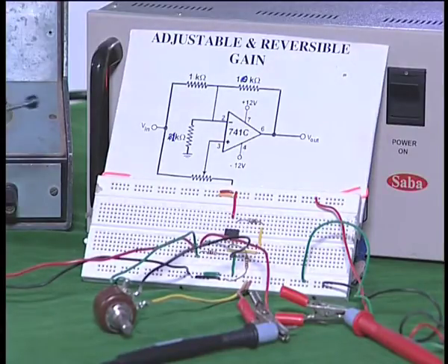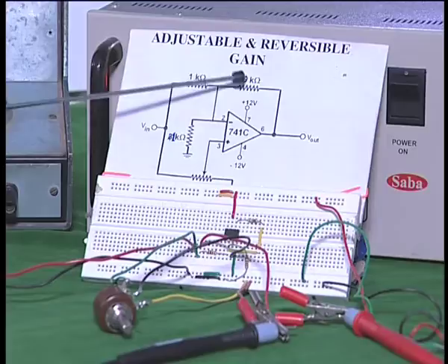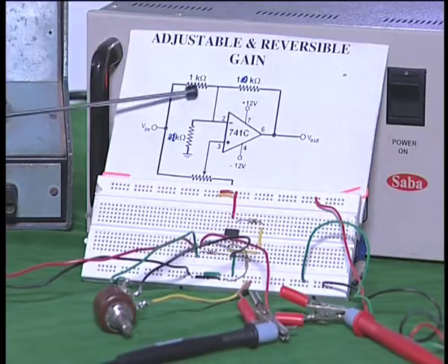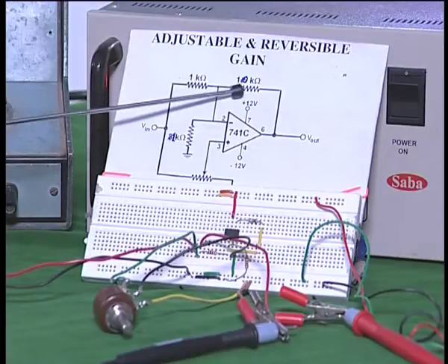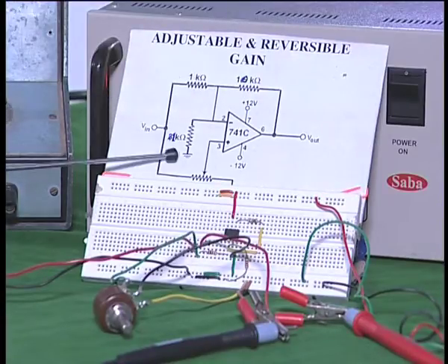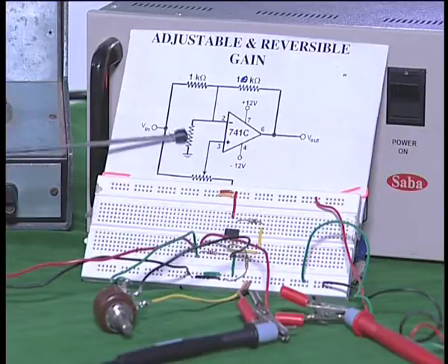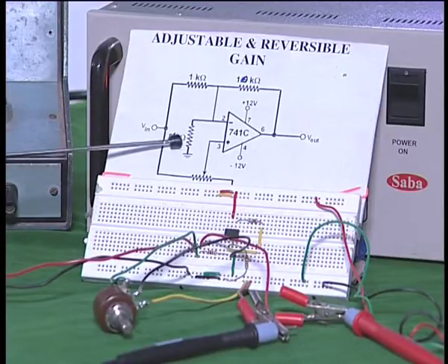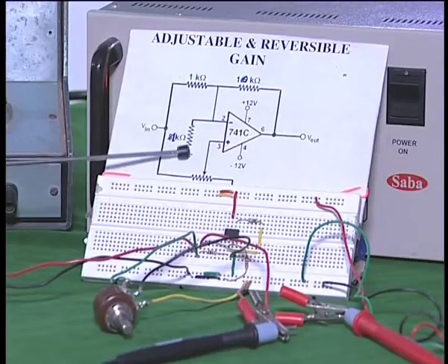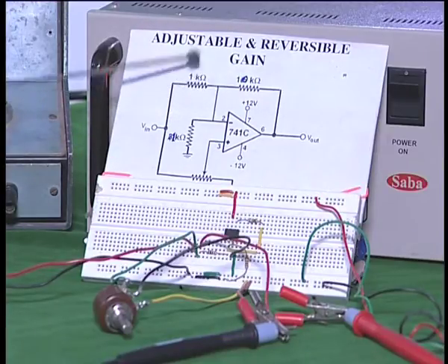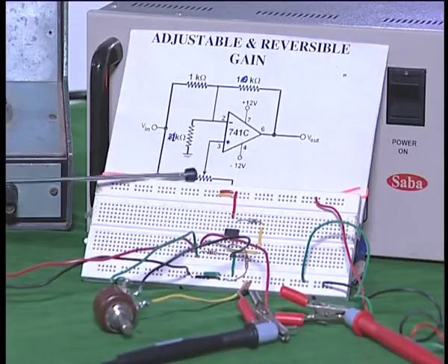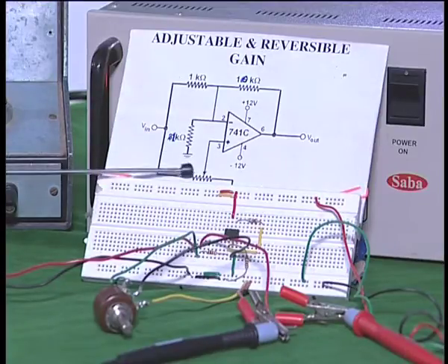Now, you can see the circuit here, it is the same as what I have shown you earlier. So, I have NR is 10k, the R is 1k, therefore, n is 10. This is 10k resistor, this is 1k resistor, and this is n by n minus 1 times R, and because n is 10, 10 by 10 minus 1 is 9, 10 by 9 times R, R is 1k, therefore, 10 by 9 is nearly 1k, therefore, I have put it as 1k. So, this is 10k, this is 1k, this is 1k also, and here I have a potentiometer which can vary from 0 to some value, usually it will be a 1k or 2k resistor here.